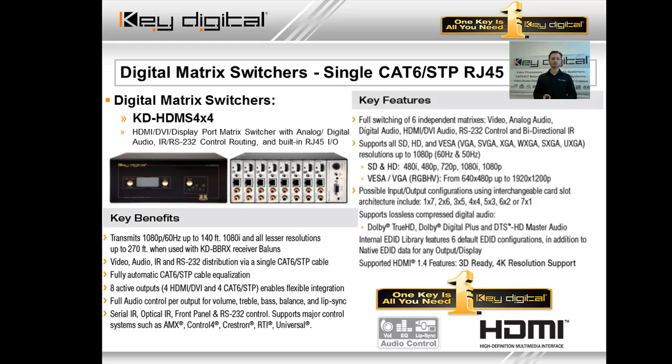This HDMS 4x4 is a video, audio, IR, and RS-232 matrix. IR and RS-232 are actually independent of each other and bidirectional, simultaneous in fact. So this goes beyond, again, HDMI video and audio only to offer a whole lot more. You have HDMI and RJ45, they're both active simultaneously on the output side. So are the RCAs there, and we're going to take a closer look at that in just a second.